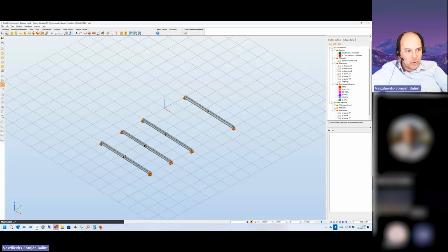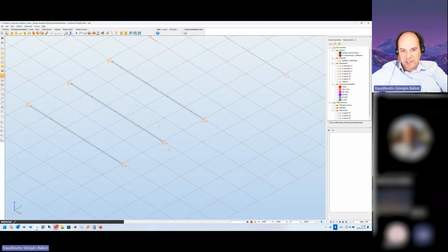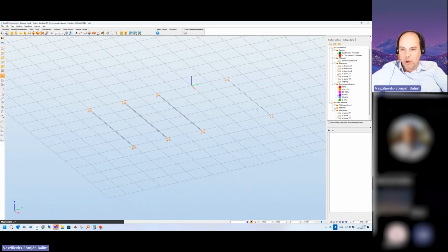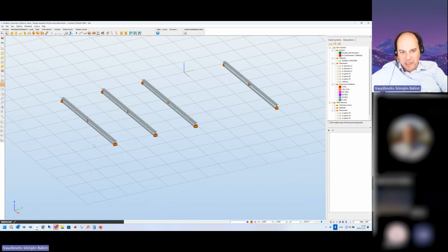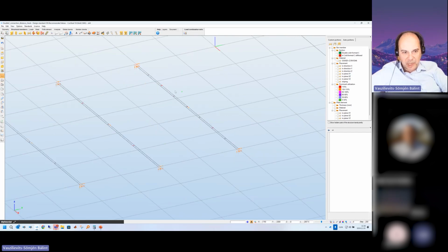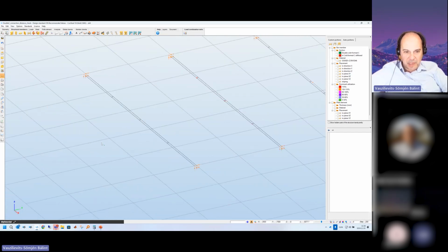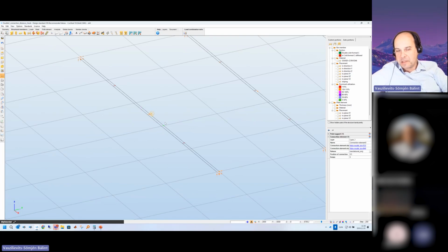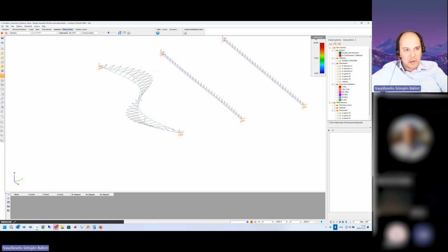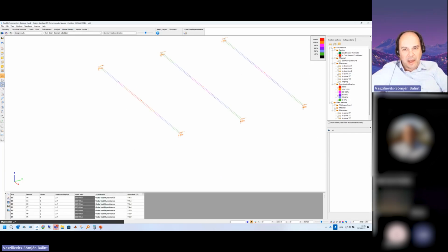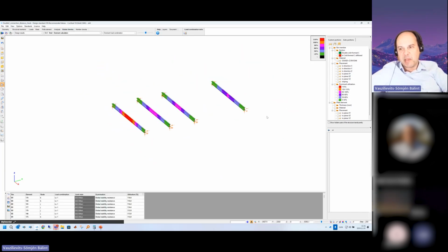What you can also do is some experiments in Consteel. Here I made a small comparison. On the right side, this model is the new approach where we have the unified model with one single reference line. Then I made three alternatives with different types of connectors, different connector spacing, and different releases along the element. Based on that, I made some calculations under the same loading.